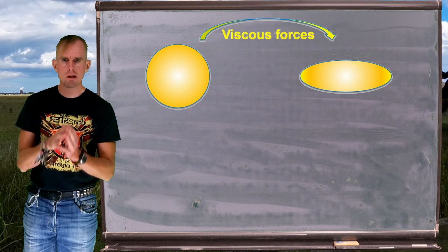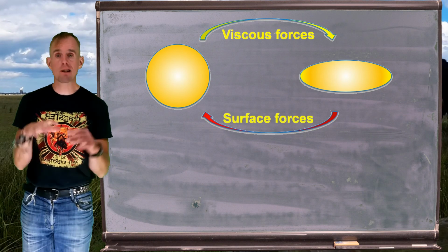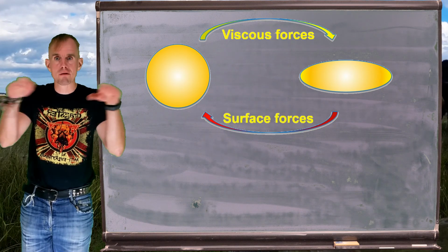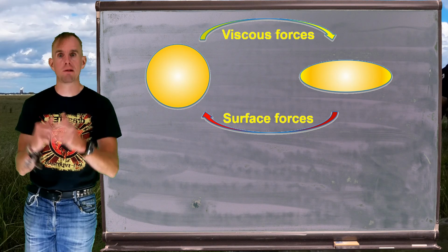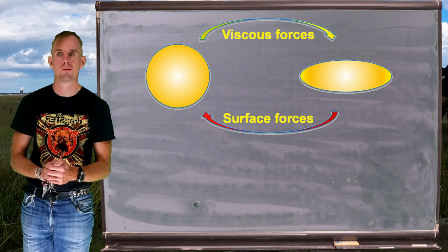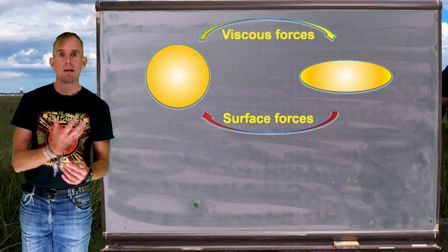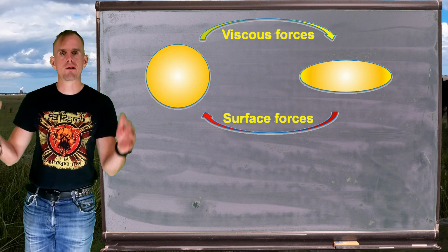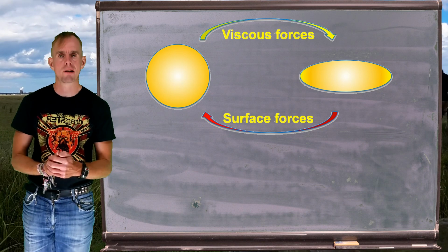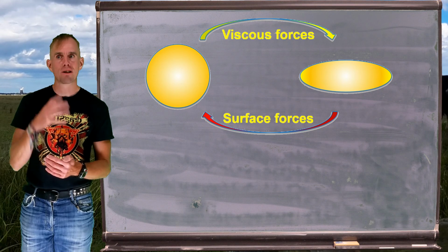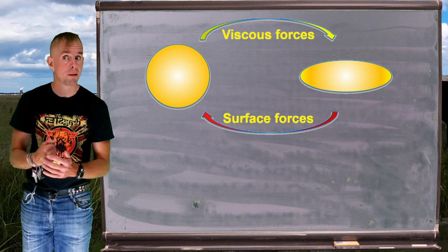Now, imagine that we stop that deformation. Surface tension takes over. Imagine surface tension, if you will, as a great big rubber band around our droplet. It forces it back to be spherical again. It minimises its surface area and it restores the original droplet shape. You could imagine that if the surrounding liquid is highly viscous, there may be some time taken for this shape restoration to occur. So maybe that should trigger the thought of emulsions might be thixotropic.